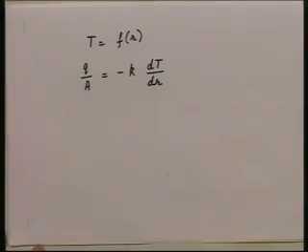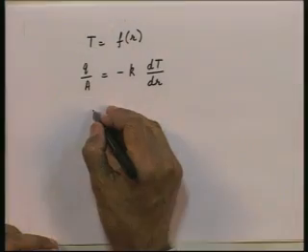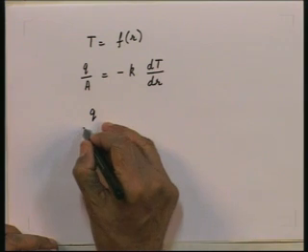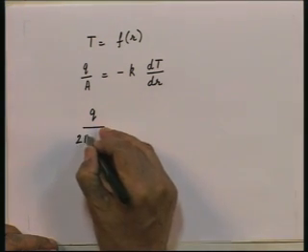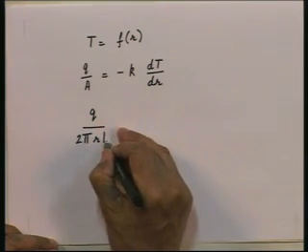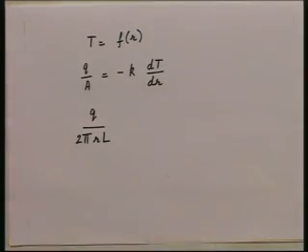Now, mind you, in a cylindrical situation, the area A across which heat is flowing is continuously increasing as we move outwards in the radial direction, unlike the infinite slab case. All right, you follow that. Therefore, for A, I will have to put 2 pi r L, where r is any radius within the cylinder and L is some length of the cylinder.